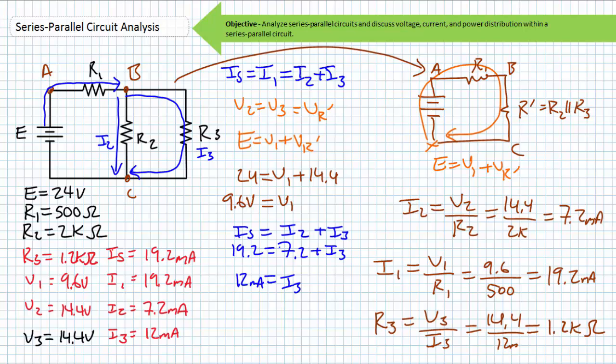All unknown quantities have been solved for using basic series and basic parallel properties only in a systematic and recognizable fashion. Visualize series parallel circuits at the nodal level and from the perspective of flowing current. Current in a single path is the same. Voltage across paths in parallel is the same. For every rise there is a drop, and what goes in must come out.